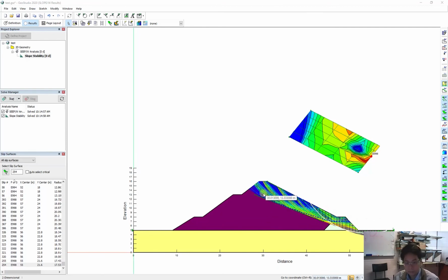The road on the top of the dam is also not big enough, and there are also no protections for the dam from the waves, and there is no inverse filter layer over here to prevent erosion, because the soil hydraulic conductivities are very different, about 100 times different from here to here, and about 10,000 times different from here to here.